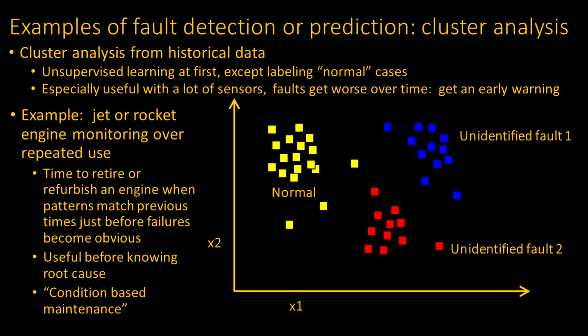This particular example isn't really real time, like our other diagnostic examples, and it may be handled by a maintenance department rather than an operations organization. But it does illustrate the principle. This particular use has been called condition-based maintenance also. By the way, when the clusters can be labeled with specific fault names, then the method supports fault diagnosis as well as detection, unlike a lot of the model-based approaches we just talked about, because they only model normal operation rather than including operation with faults.